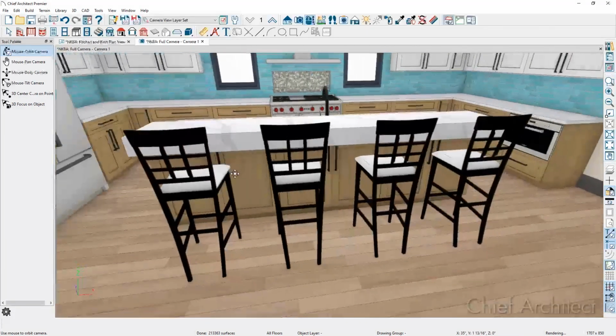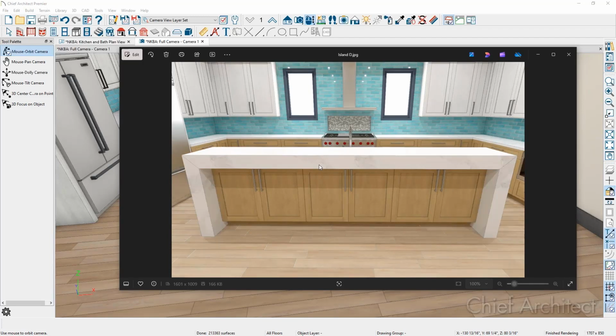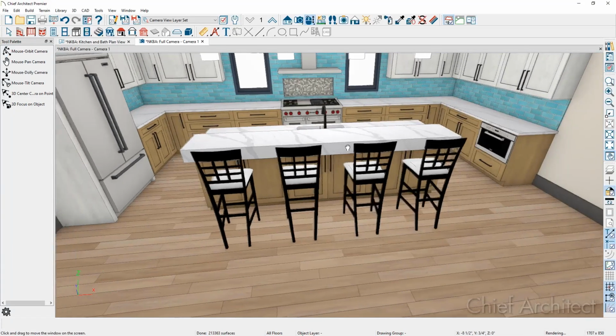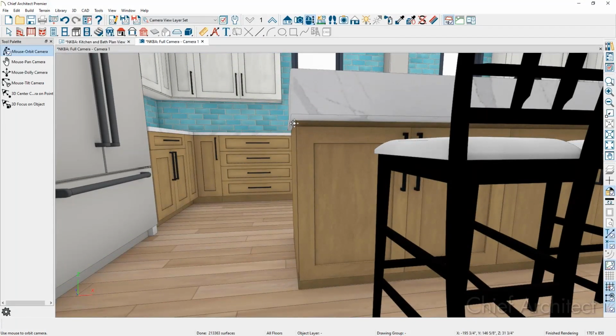And then for our last countertop design option available to the client, we will go ahead and waterfall it down to the floor. So before we waterfall it, we need the countertop overhang to match the countertop thickness to make sure that's not merging through the cabinet. Currently the countertop is overhanging by 1 inch, so we need to bring it out another 5 inches and then we'll drop it down to the floor.